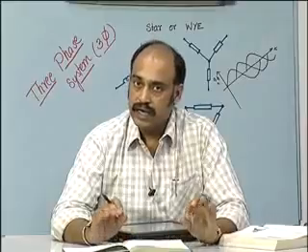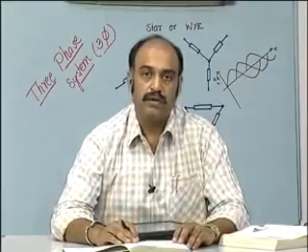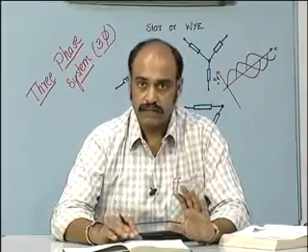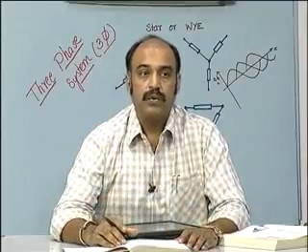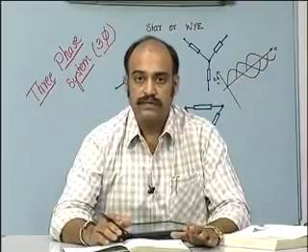That would give you the equivalent total power drawn by the 3-phase load. If it is a 3-phase 4-wire system, then just connect 3 watt meters and add up the 3 values to get the power. We stop here and continue the next class with 3-phase transformers.